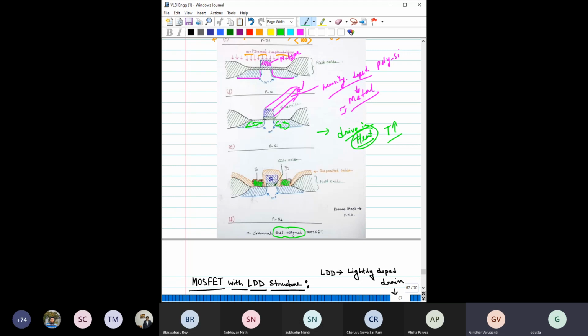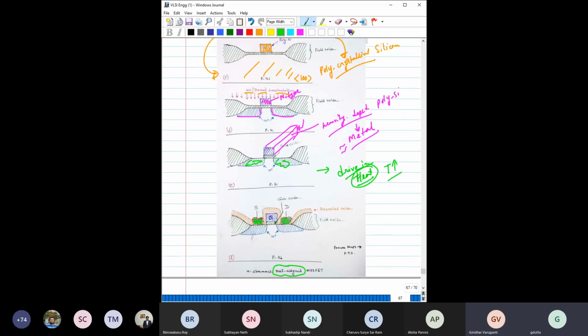Okay. So we started with the metal gate. In between, we used polysilicon as the gate material. Then again for modern technology, we are using the metal gate. So it is metal, poly, metal in terms of timeline. Okay, I hope this part is clear to you. Self-aligned process: what is the advantage compared to the gate-last process?